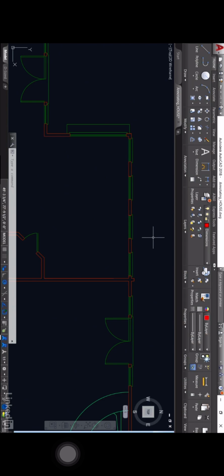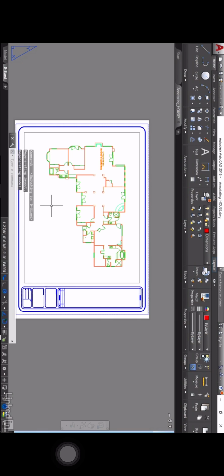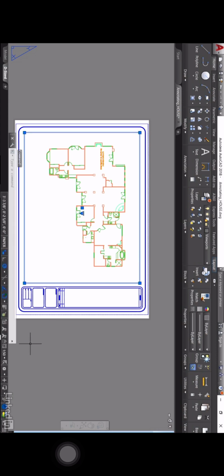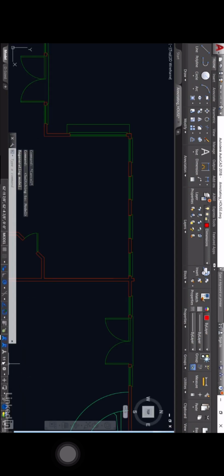And what that allows you to do is to jump into something like the Layout tab, as I've done here. And what you can do is specify a scale that corresponds to the viewport. So if I click on this viewport here and look at the status bar, it's at 1 to 50. So what I can do is hit Escape now and deselect that and go back to the Model tab and change my annotation scale here to 1 to 50. That means that any annotative dimensions that I place will adhere to that 1 to 50 scaling, both in the model space and in the Layout tab, and it just maintains consistency of the size of the text, size of the arrowheads, and so on. So we've got the dimensions layer set, we've got the dimension style set, and we've got the annotation scale set.